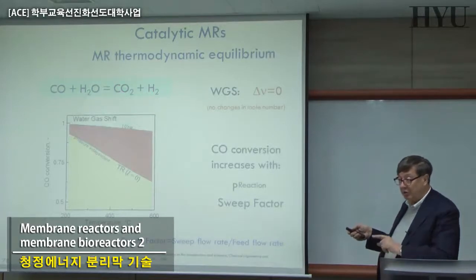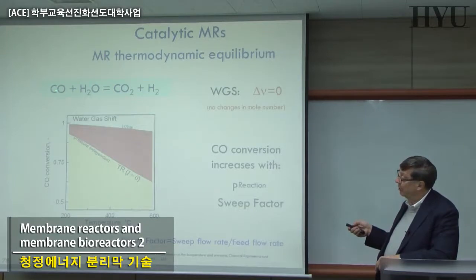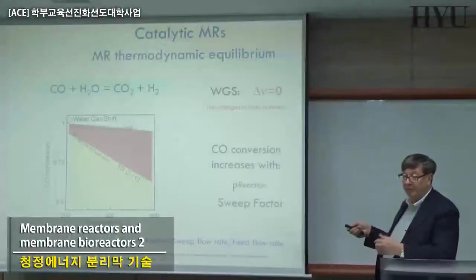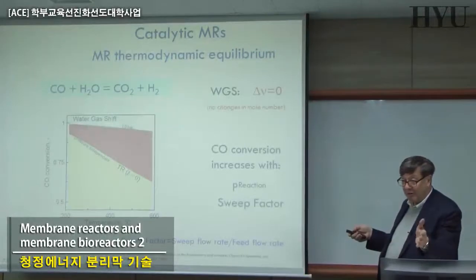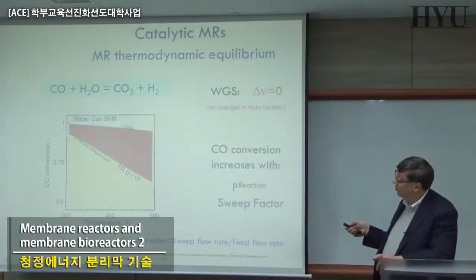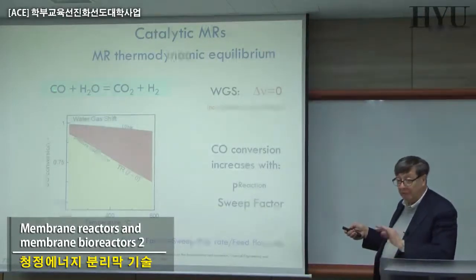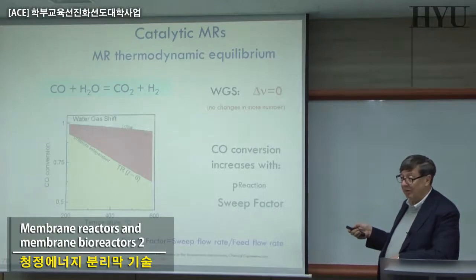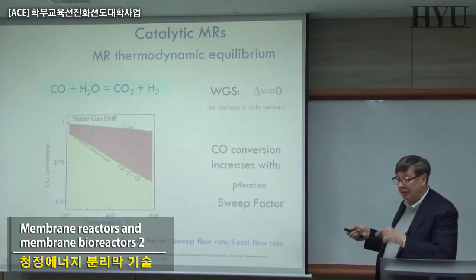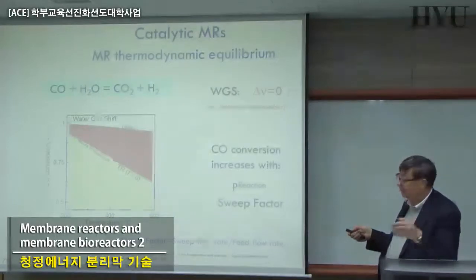This is the reaction we use upstream of the fuel cell to reduce these poisoning compounds coming from steam reforming, where we form hydrogen but together with hydrogen we also form CO. This CO poisons the electrodes that we use in the fuel cell, so it has to be eliminated down to less than 10 ppm.